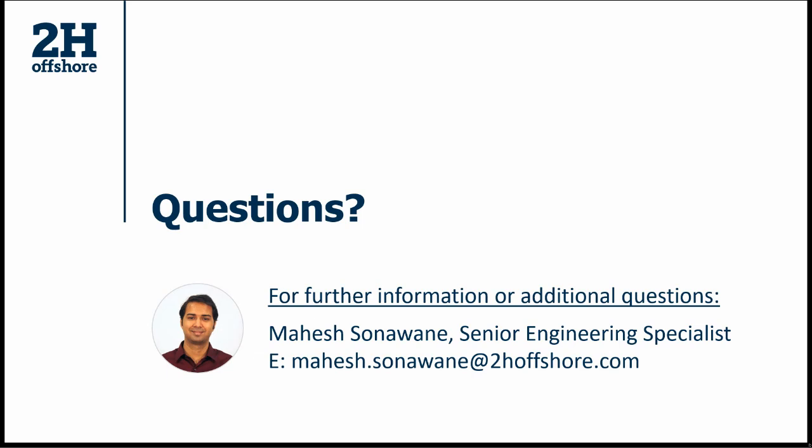Okay, thank you. Next question, has OrcaFlex been used as part of jumper design of fatigue analysis? Yes, we recently have used OrcaFlex as well. We have done this exercise where we're benchmarking different softwares. We have used FlexCom, OrcaFlex, ANSYS, and Abaqus. There is some variation in the predicted frequencies and curvatures, and that's mainly attributed to how the torsional effects are considered in these different softwares.